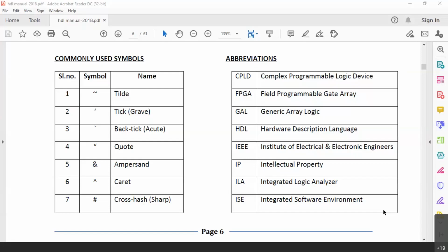For that, there is something called a netlist, a network list, which is a connection of all those gates and wires. So in the FPGA, accordingly, all those gates and wires have to be connected. For that, the Verilog code or a VHDL code has to be converted into the hardware counterpart, the circuit diagram. That process is called synthesis.